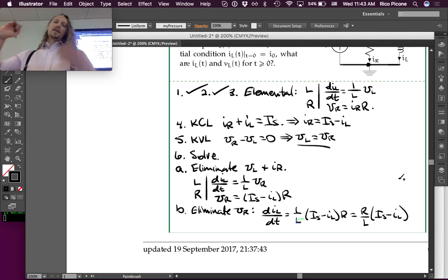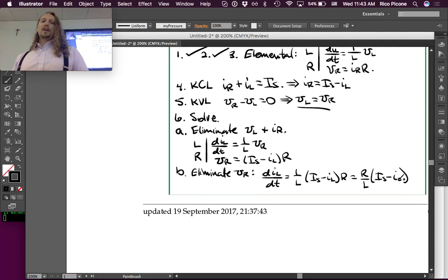So similar. It's first order. All of them look the same. So let's do the same thing we did before and rewrite it in the form that we're used to for a first order equation. And let's define a time constant again to be L over R. That's because we need to multiply both sides by L over R to get that expression out here, and that's what our time constant is defined as. So this is our definition.